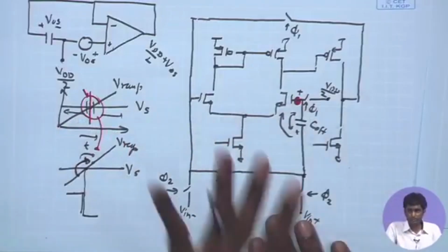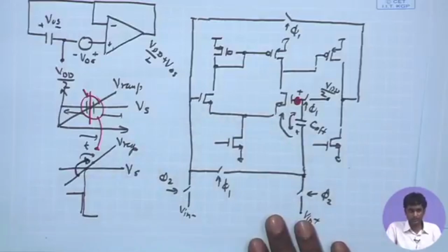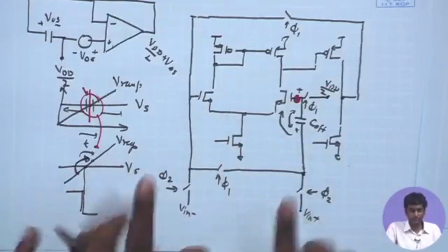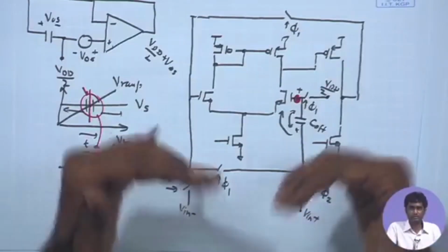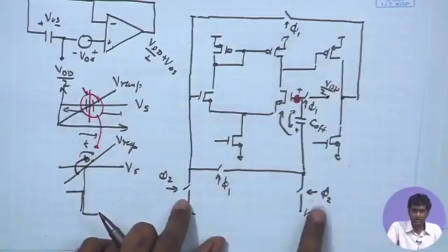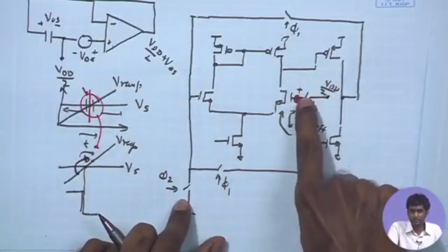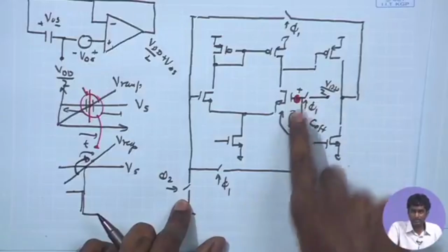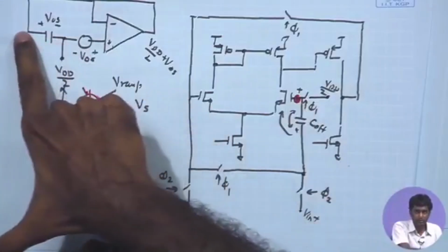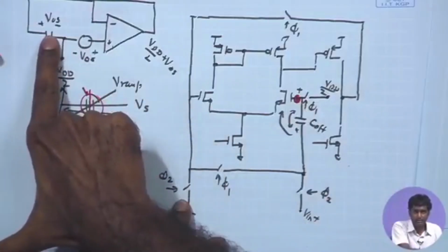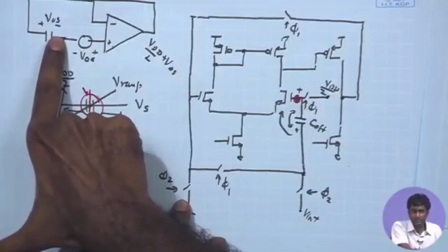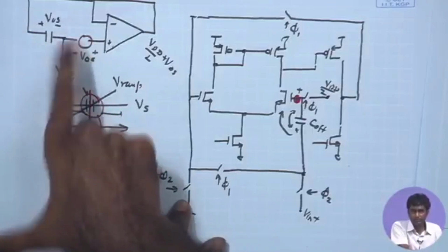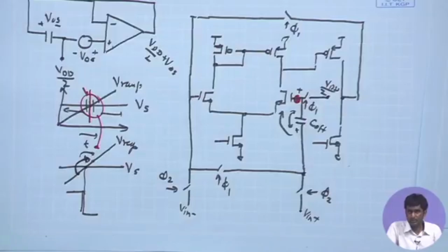So, output DC point we need not worry about it in this case. Is it clear? Input DC point definitely we can, based on the capacitor stored charge in the V in, say that this is just going to have a jump. This is V in, this is going to be V in minus V offset. The moment you apply V in over here, this voltage is clamped across the capacitor, V in minus V offset plus V offset. Therefore, that is well settled.